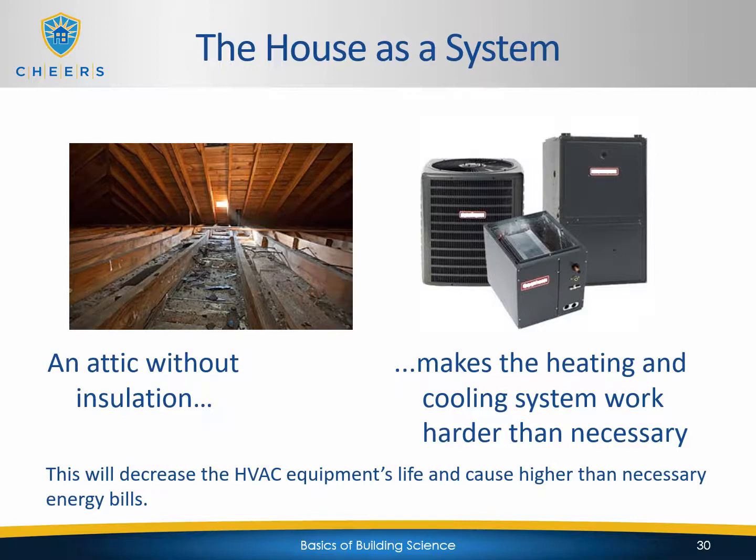So for example, let's talk about some interconnectivity issues, right? An attic without insulation makes the heating and cooling system work harder than necessary. This will decrease the HVAC equipment's life and cause higher than necessary energy bills. Let's say in the winter, again, you're heating up your house, there is no insulation in the attic, that hot air will just rise up and it will leak out, right? It will transfer right out.